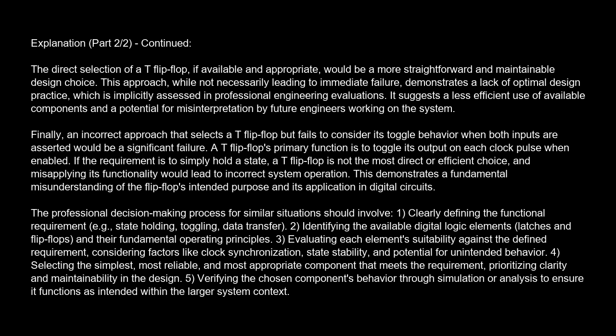The professional decision-making process for similar situations should involve: 1. Clearly defining the functional requirement, e.g., state holding, toggling, data transfer. 2. Identifying the available digital logic elements, latches and flip-flops, and their fundamental operating principles. 3. Evaluating each element's suitability against the defined requirement, considering factors like clock synchronization, state stability, and potential for unintended behavior. 4.